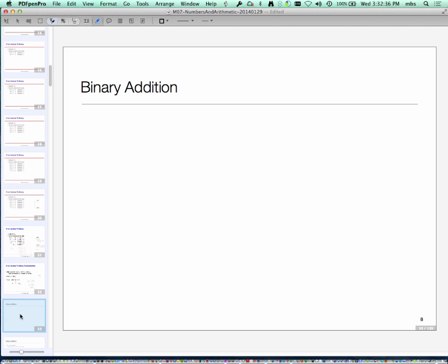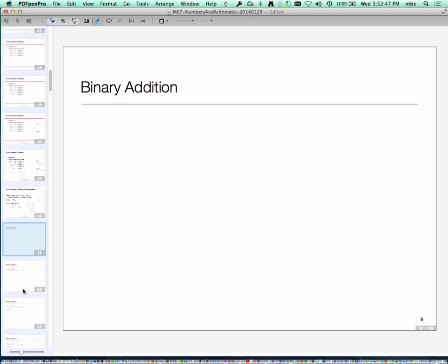So what we are going to look at is designing combinational logic which takes inputs, and I'm telling you that those inputs represent a binary number. We have to design the logic to add them. If I have 2 1-bit numbers, the cases are: 0 plus 0 is 0, 0 plus 1 is 1, 1 plus 0 is 1, 1 plus 1 is what? 1 plus 1 is 1, 0, right? Because 1 plus 1 results in a carry. So it has to be the number 2, much like our decimal one.